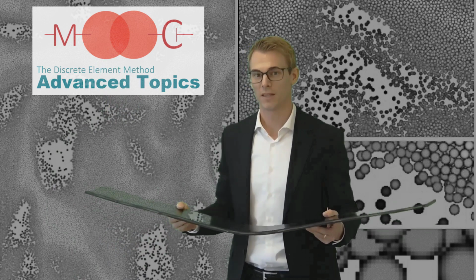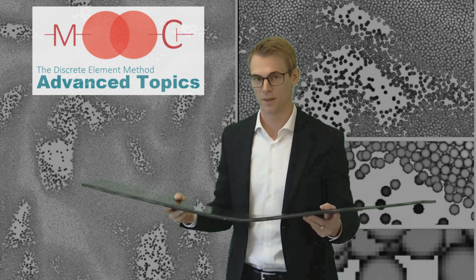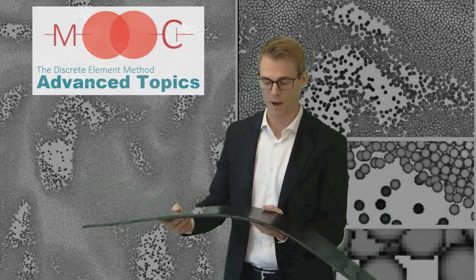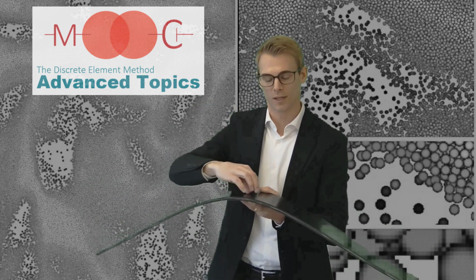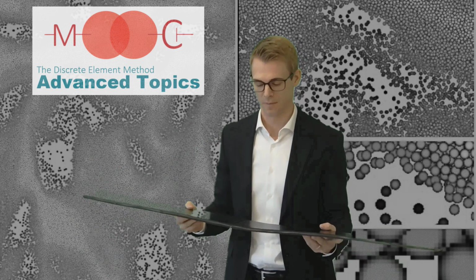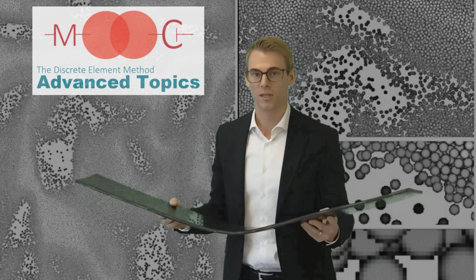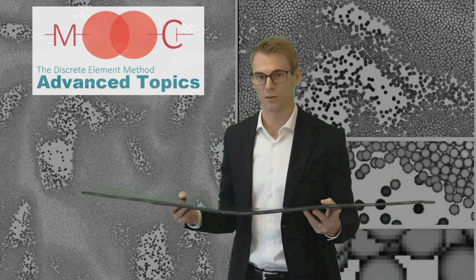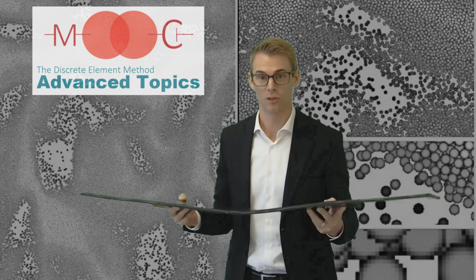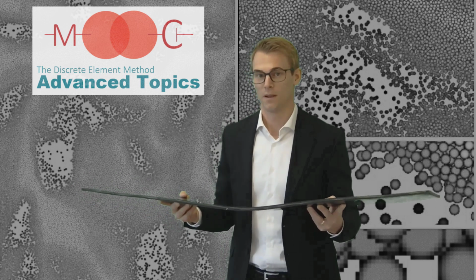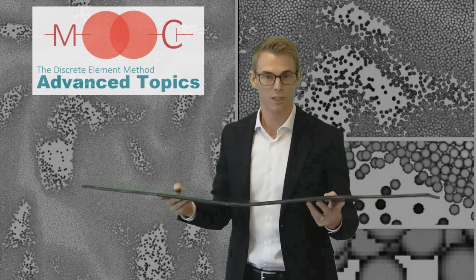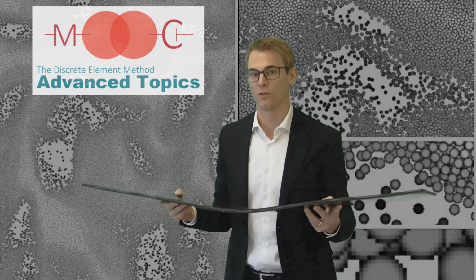Conventionally, conveyor belts are modeled as rigid surfaces with an advanced contact model which induces a movement in particles when they get in contact with the belt's surface. This may work for simple applications, for example, when the belt's deformability is not in focus, for example, when the belt is only used to feed a system. However, when the belt's flexibility is also in focus, this rigid belt modeling does not work, of course.